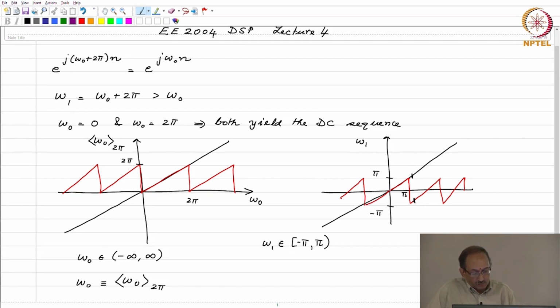then of course from 0 to pi it is the same curve, nothing changes because it is positive. But if you look at the value of omega 1 beyond pi, then if you look at the modulus, the curve looks like this. So this also gives you a feel as to why the frequency decreases. From 0 to pi, the rapidity of the oscillations increases. At pi, you reach the highest frequency, and then beyond pi, the frequency actually decreases, as you can see from the modulus function, that is taking the absolute value of omega 1.